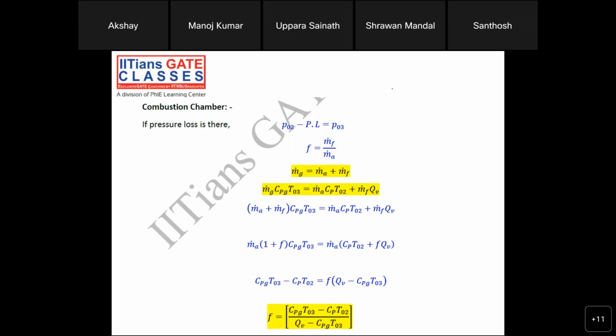Whenever you talk about total pressure loss, to overcome the total pressure loss you are doing so many exercises. Why do you have to do those exercises? Because the total pressure is the direct measure of the energy content of the flow. If you are losing total pressure, that means you are losing part of the energy in a non-useful way, right? So that is why it is a very important aspect. We will be dealing with total pressures.